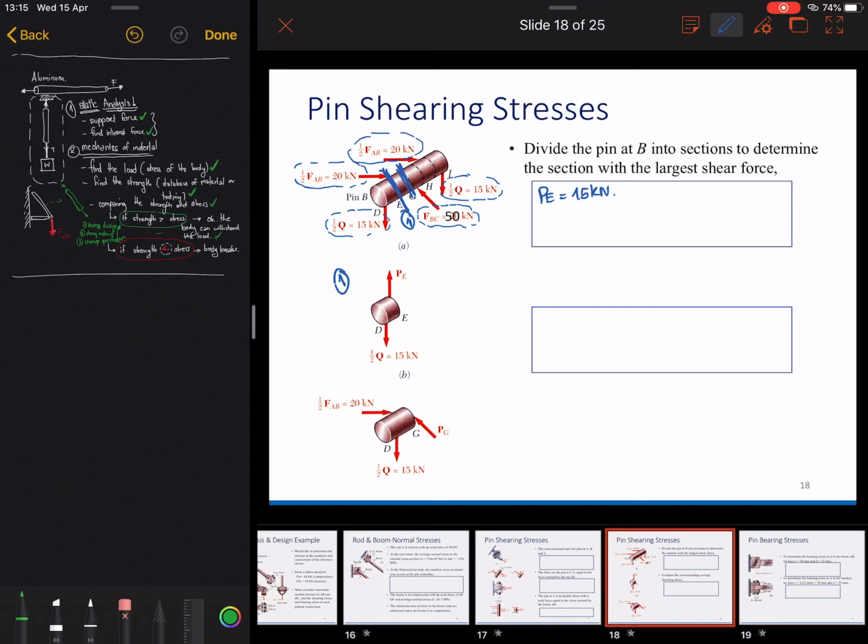Okay, then here's the first shear force, and then you cut also here. Then next, this is 2, then you second cut here, you got this kind of equilibrium, and then if you connect those arrows here, you will get 20, no, this one is 15, 20, and then you know from the triangle rules this is 25. Okay, 15, 20, 25, because this is 3, 4, 5 as a triangle rule. So we know that PG equals 25 kilonewtons.